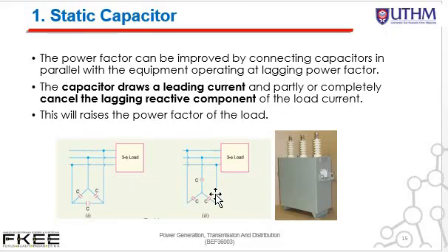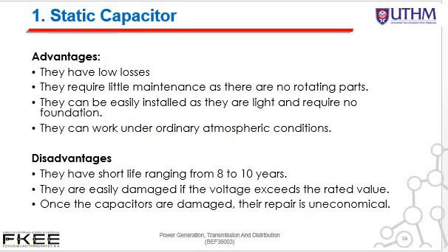So we add a star or delta configuration capacitor in parallel with any three-phase lagging load. By doing so, we can improve the power factor of the system. However, despite having several advantages, a static capacitor has a short lifespan and is easily damaged by over voltage.